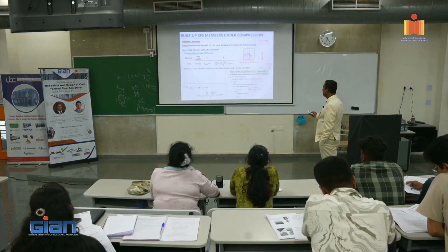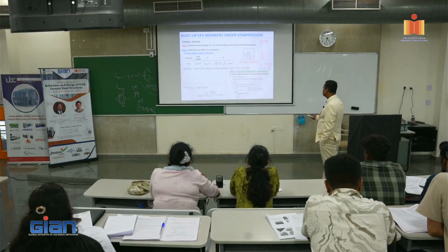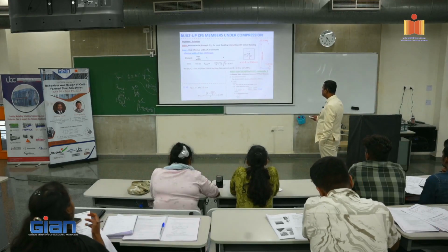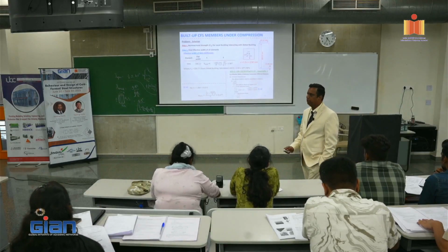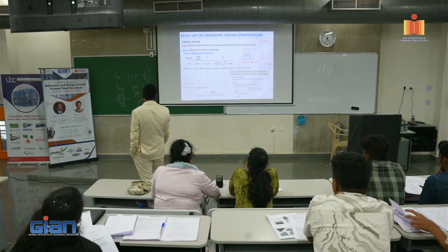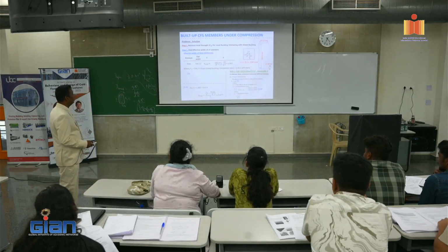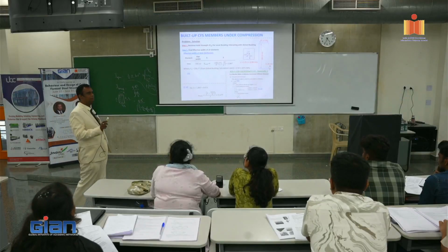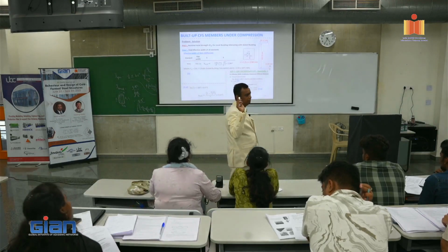Since lambda equal to 1.847, which is obviously greater than 0.673, we have to choose a reduction factor based on this one. The reduction factor is given by (1 minus 0.22 by lambda) divided by lambda. I am sure you are aware of this from the tutorials. This is the reduction factor for the web: (1 minus 0.22 divided by lambda) equals 0.477. So what do we do here? Reduction factor into W. What does it mean? Only 47.7% is effective. The rest is going out, so it is not effective.